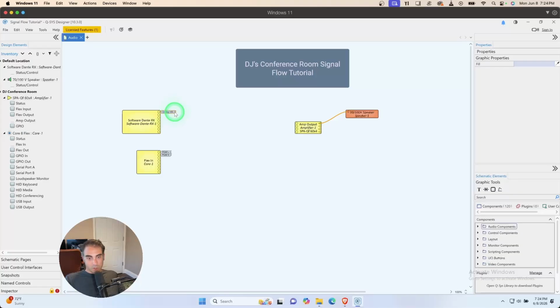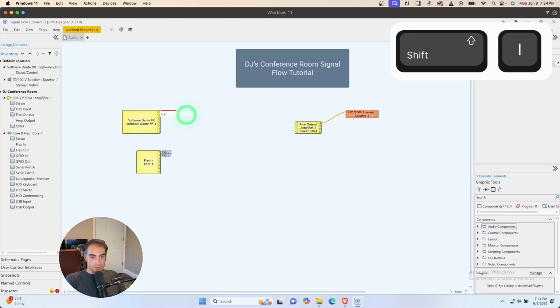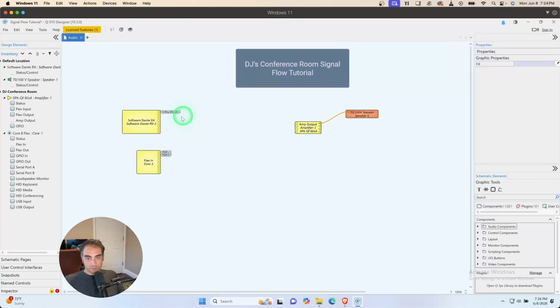Now you notice I just did one channel. These mics can typically support up to 8 lobes or 4 lobes. Sometimes they mix down to 1. It's been more common now to utilize the internal mixing inside of the microphone because it does a much better job than it used to. And it also saves you on your Dante channels and your DSP processing and everything else. You can fit a lot more. So we're just going to say that this is a mix. So ceiling mic mix.